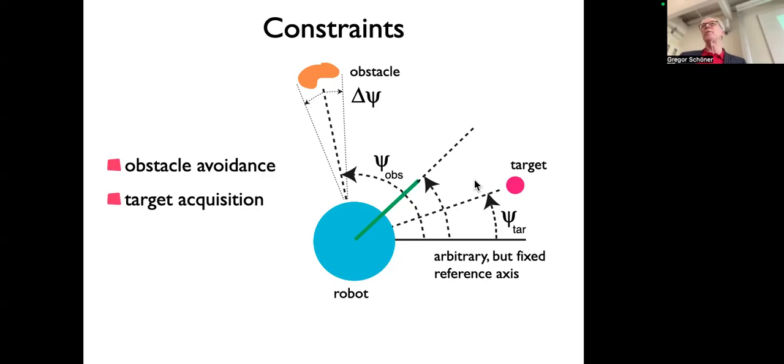So it doesn't really matter in which reference frame that is. For obstacle avoidance, you could say, well, maybe there's a certain direction in space in which I'm detecting an obstacle, and that direction can be characterized by this angle toward the obstacle. It might typically be a range of angles because my obstacle might be a whole region in which there are objects. And then that's a range of values to avoid. I don't want to go in that direction. You see immediately that this isn't good to do very rigidly, because if you avoid any direction in which there's something, then you could only navigate in infinitely free space, right? So there will be some modulation with how long that distance is to that obstruction, and we'll come to that. But we can express these two constraints in terms of that variable.